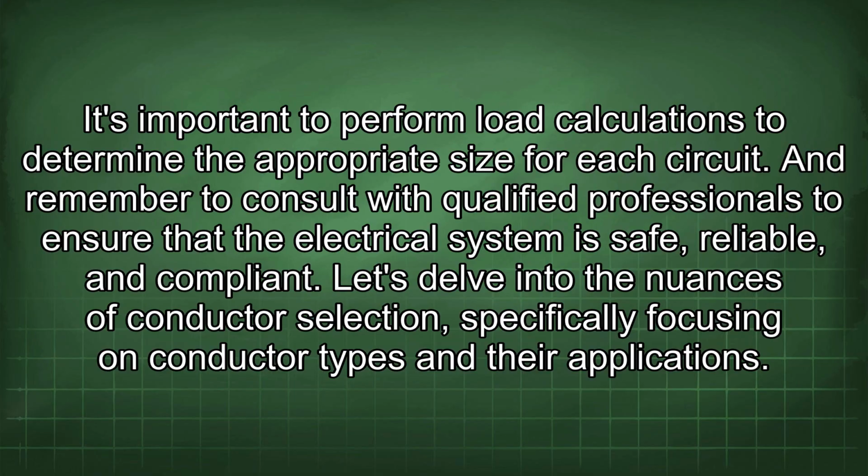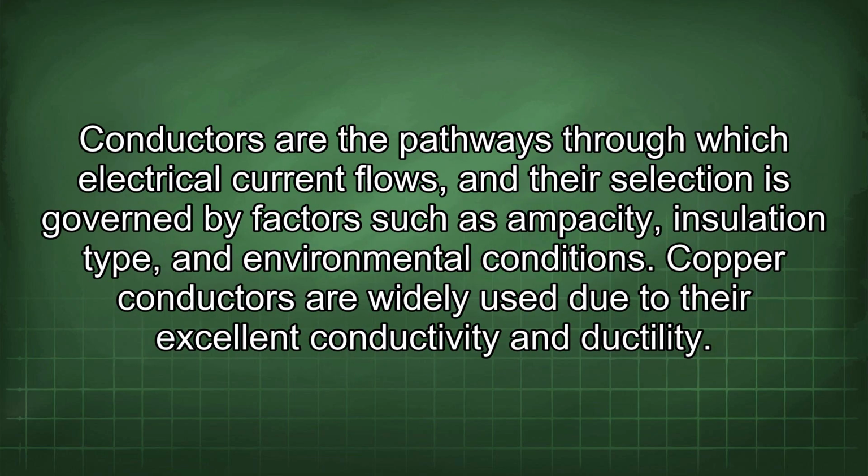Let's delve into the nuances of conductor selection, specifically focusing on conductor types and their applications. Conductors are the pathways through which electrical current flows, and their selection is governed by factors such as ampacity, insulation type, and environmental conditions. Copper conductors are widely used due to their excellent conductivity and ductility.